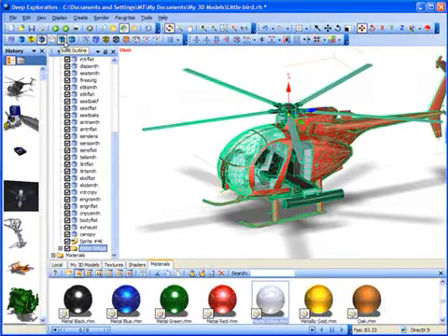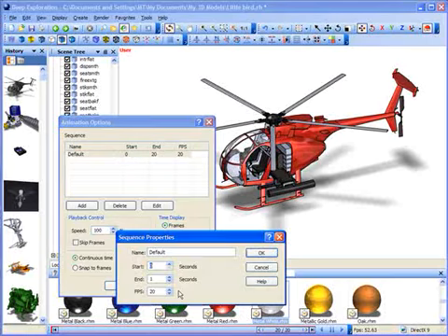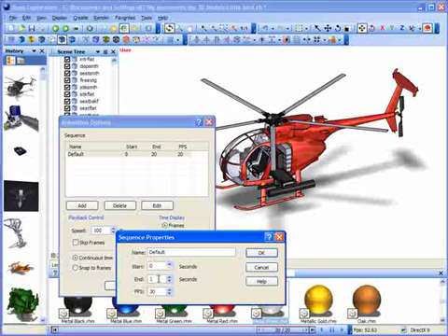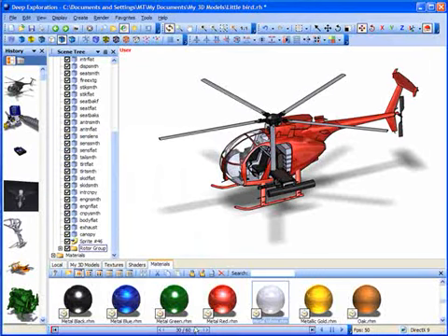So the next part of the demonstration will show how we actually animate this. To animate things, we need to create keyframes. So we're going to use the Edit Keyframes tool. We click on this, and we see that down below we've created a little animation area. We've got 20 frames. We can click on this, we can edit it. We may in fact want to change our frames per second to 30, and we'll make it a 2-second animation, so that will result in 60 frames.